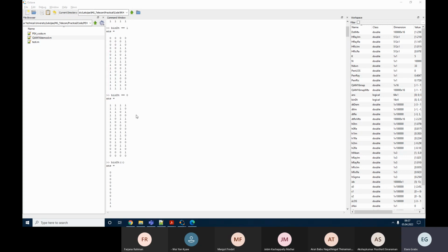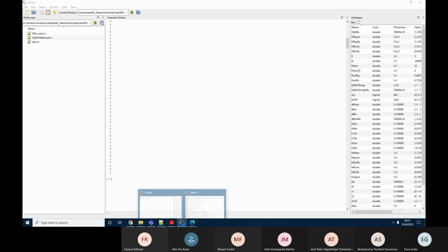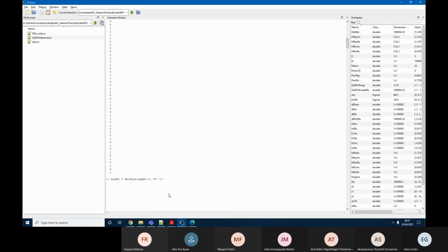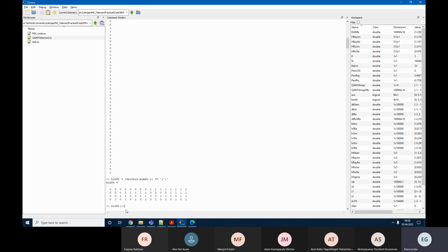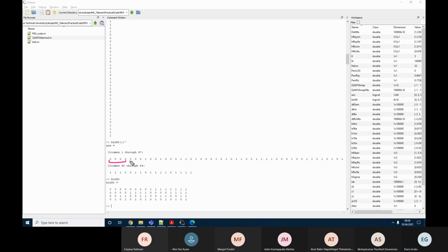What we need to do is quite the opposite. In fact, we have to transpose it to make it like this, to actually force our symbols to be located in the columns. So here we have first symbol, second symbol, and so forth. Now if we unwrap this matrix into a vector, everything will be fine and we'll get the correct sequence of binary data. So bin data unwrapped, and accordingly like this. Yes, so here you can see the first symbol, the second symbol, the third symbol, and so forth.